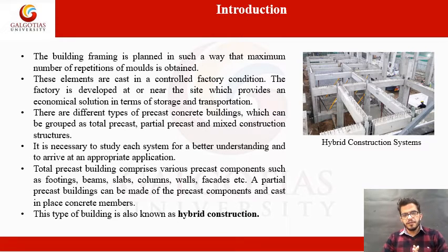Moving forward with the introduction, a building which is designed in a prefabricated system is also called hybrid construction. A building framing is planned in such a way that the maximum number of repetitions of molds is obtained. These elements are casted in a controlled factory condition.